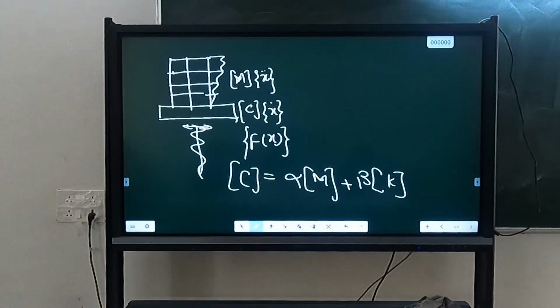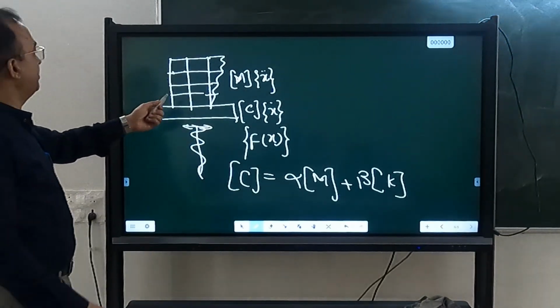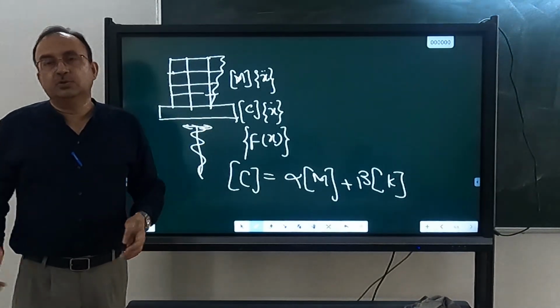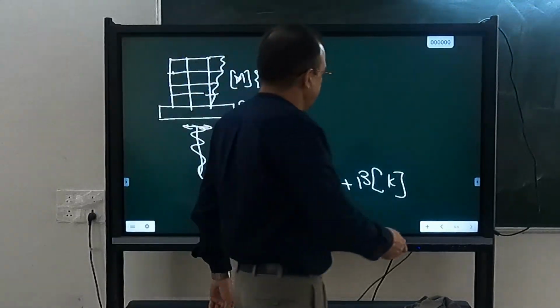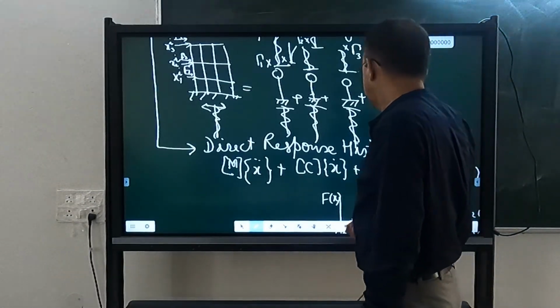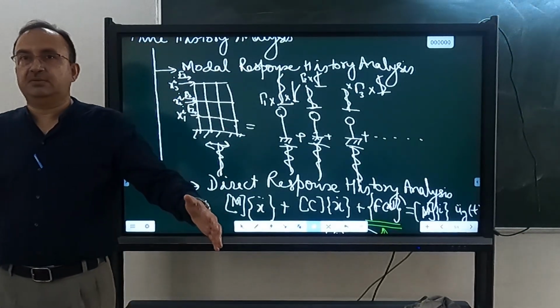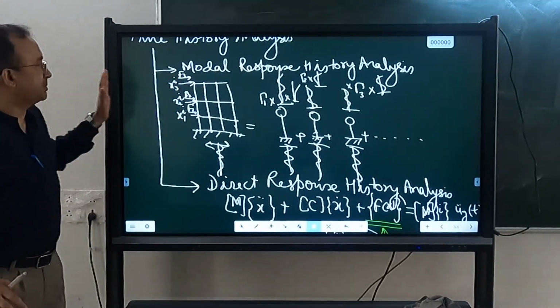Only for those two shake tables will you find that in recent years there are publications. Other shake tables are being used for small things, for example, if I want to test a false ceiling or some small non-structural component, that type of testing can be done. But real structural testing of a building or bridge is not possible here unless our shake table is very large. So what is the solution? One of the solutions is this, where rather than shaking the whole structure, we make the structure fixed base and apply the displacement.